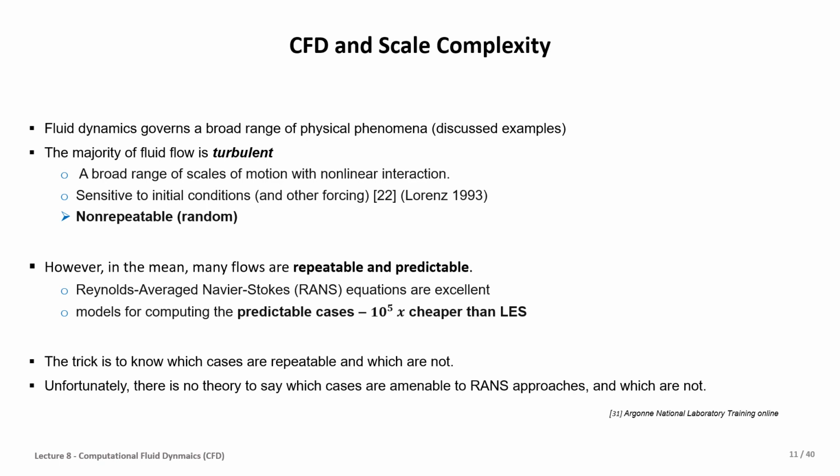Because of this difference, usually the RANS method is used in industry, and it provides the sufficient information that is required for engineering design, and it costs much lower than LES and DNS. The next one, usually used in research, is LES. DNS, however, is used in some research, but because of its computing cost, we try not to use it as much as possible. But in essential cases, DNS is used.